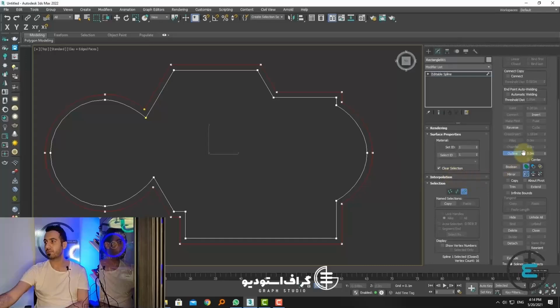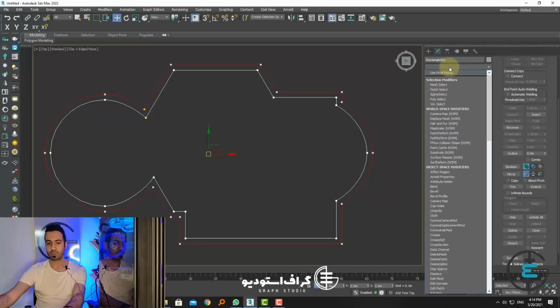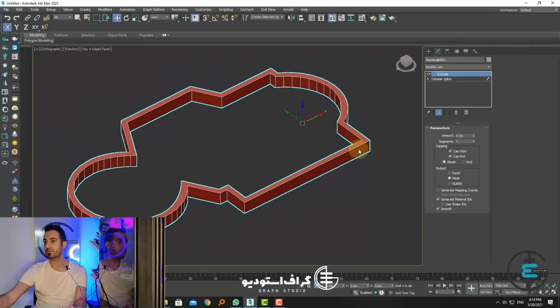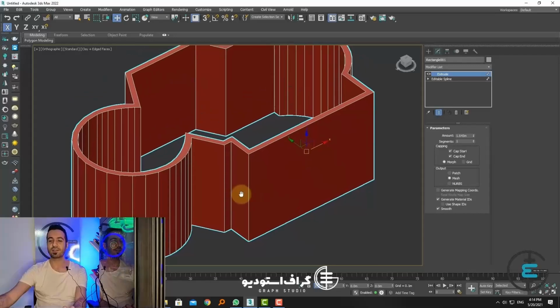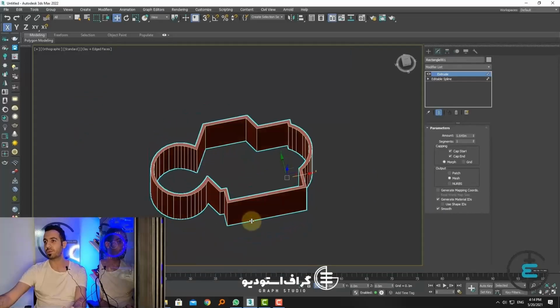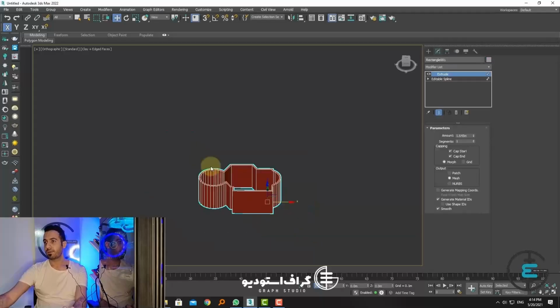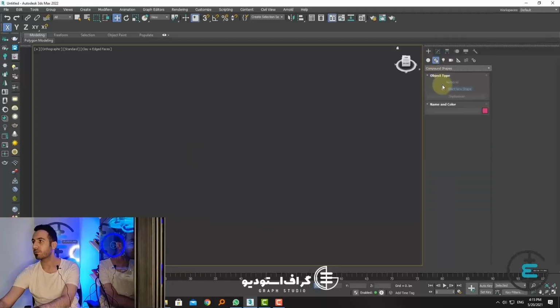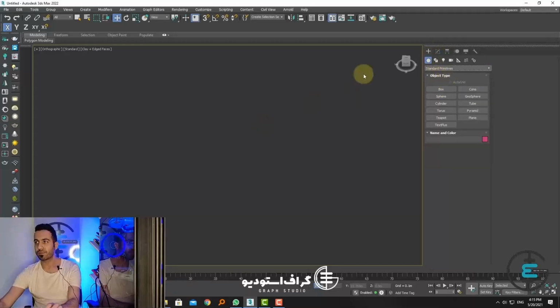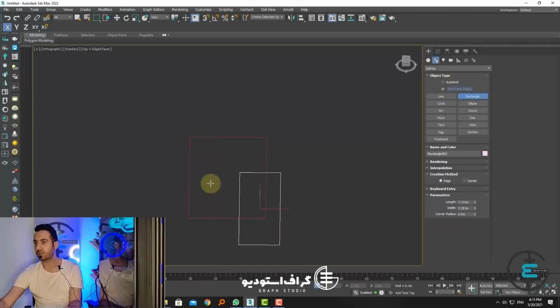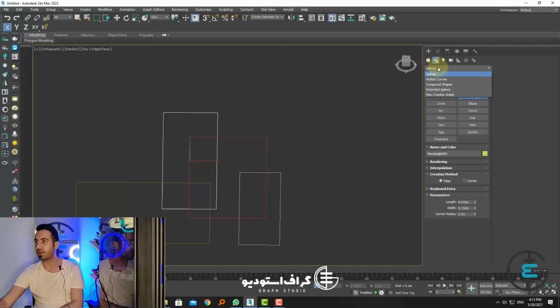Well, here guys, I come in the top view. I draw a shape like this, one in this shape, one for example in this shape. I'm going to spline in the compound shape section. ProBoolean, for example, union, add operation active. I say take this one away from this one, from this one, also from this one. How easy and practical. Or now, I say to take the intersection of these. Their share would be exactly this part.